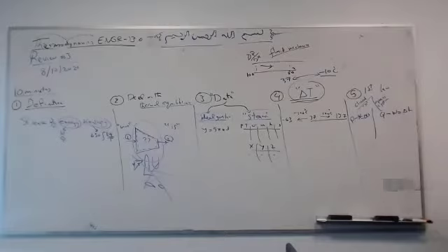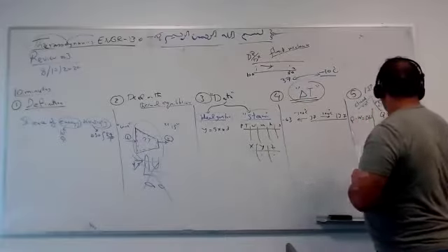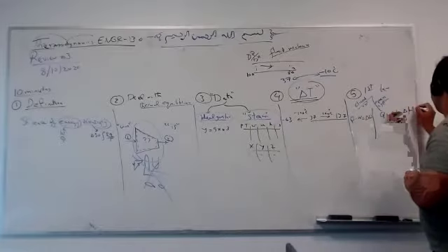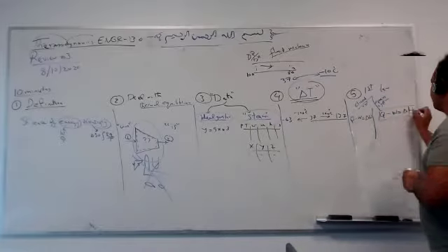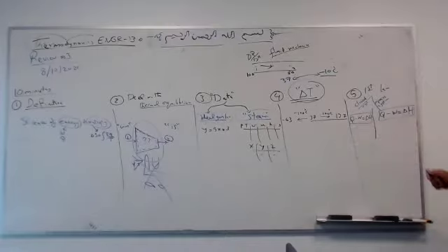That's always correct. Flow in a tank, piston cylinder like the Otto cycle, Rankine cycle, diesel cycle, dual cycle, Ericsson. So Q minus W equals delta U. Can you see that, guys? Q minus W equals delta U. Q minus W equals delta H. So this is the open system, this is the closed system. We have two systems: closed, where no mass crosses the system; open, where mass crosses the system. So heat minus W equals the change in internal energy. That's called the first law of thermodynamics for a closed system. Just remember this. I'll give you an example.